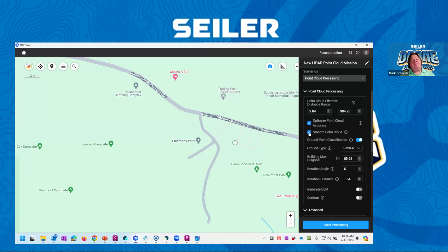You have algorithms in here to smooth that, to get to that middle third to 2/3 data in the center, your average elevation, and pull that data out. But certain algorithms like DJI Terra will end up rounding out sharp objects like curb and gutter. So you have to be careful of using that kind of tool.